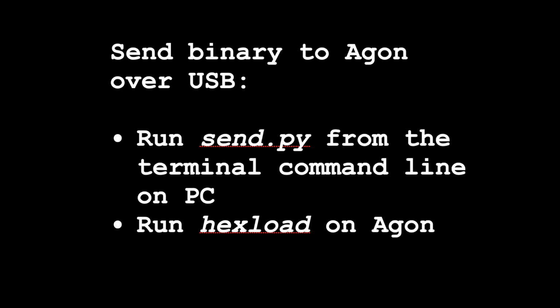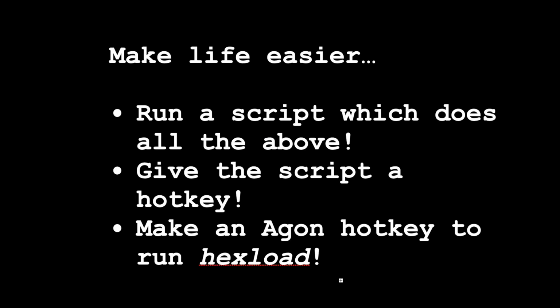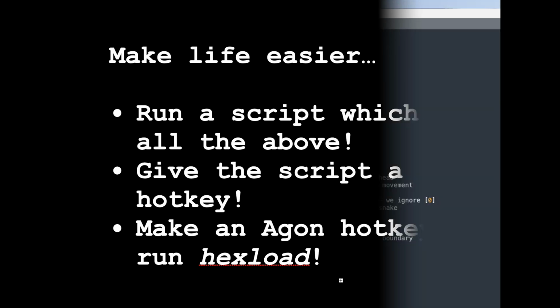The send.py script, which is available with the hexload download, sends the data from your PC to the Agon. But that can all be a bit of a hassle. Try writing a script which does everything above. Give your script a hotkey, and even give the Agon a hotkey to run hexload.